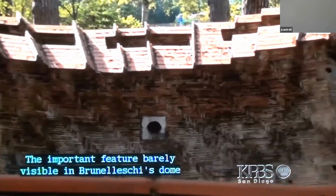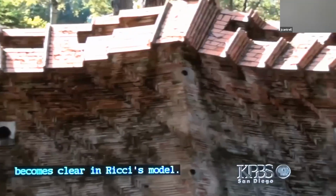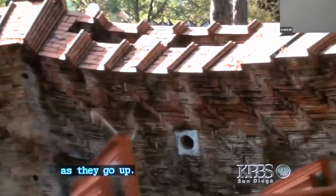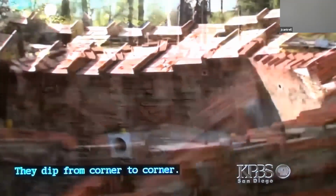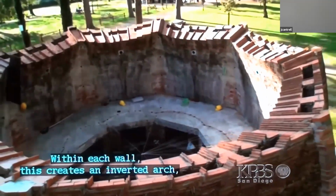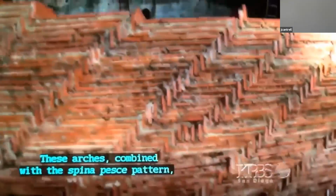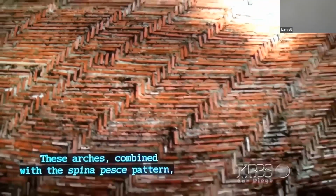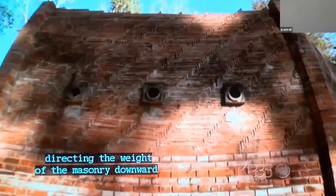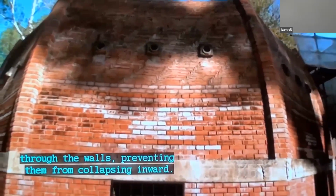The important feature barely visible in Brunelleschi's dome becomes clear in Ricci's model. The tops of the walls don't follow a straight line as they go up. They dip from corner to corner. Within each wall, this creates an inverted arch, one of the most stable forms in architecture. These arches, combined with the spina pesce pattern, keep the bricks firmly in place, directing the weight of the masonry downward through the walls, preventing them from collapsing inward.